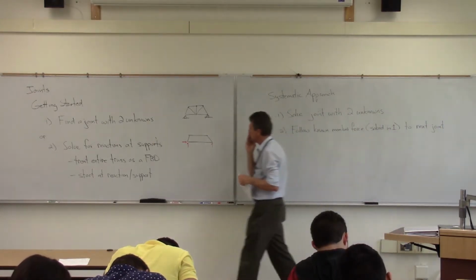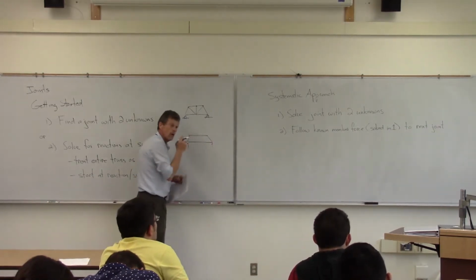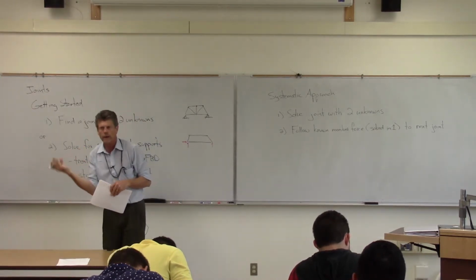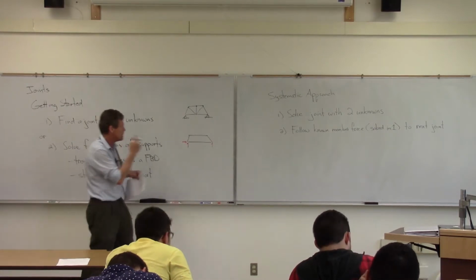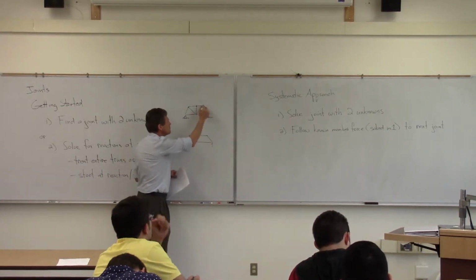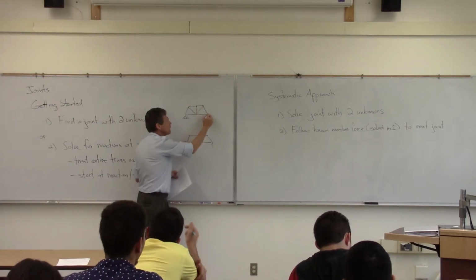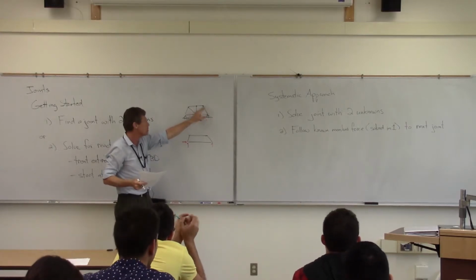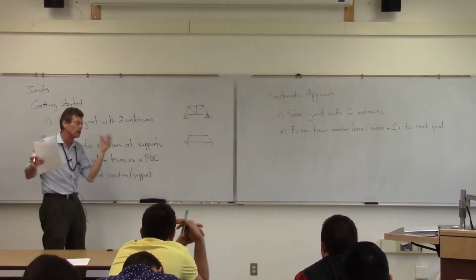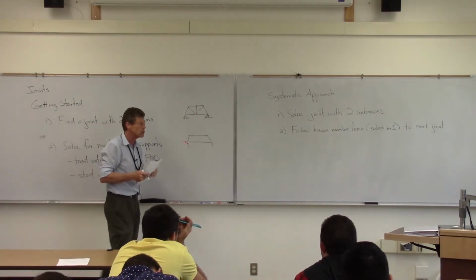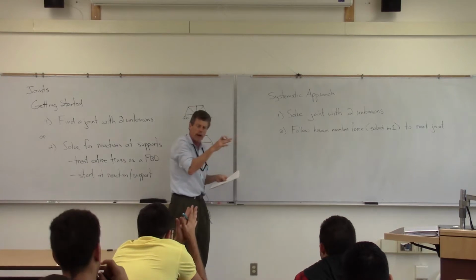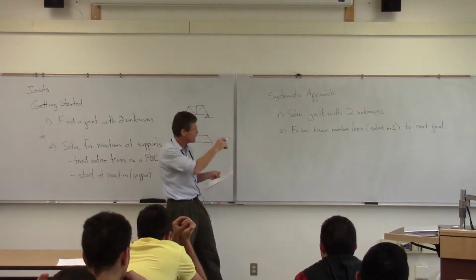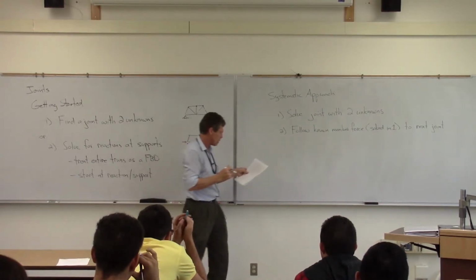Okay, then once we've solved for the forces in these members, since they're two force members, I know the force at the other end: equal, opposite, and collinear. So I can follow that up to the next joint, in this particular case to this one. If I solve for this known force here, then I come up to this joint. I've got this one member force now, and then two unknown member forces. So now all of a sudden I've got two unknowns, and I can use my equations of equilibrium there. So we're going to take what we've done and walk our way to the next set of joints, following the members that we just solved.